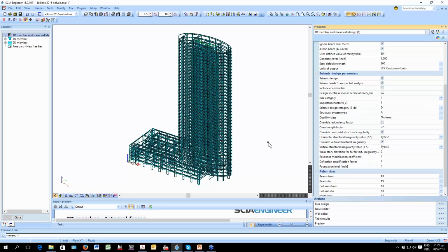If you, by mistake, give the 0 of your model and you have a basement box, you actually have a more severe check than you would have, because, as you know, the seismic shear gets inverted at the starting of the foundation box. We also have typical rebars from which to choose for the design, and then we select Run Design.